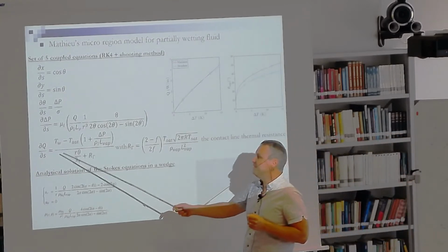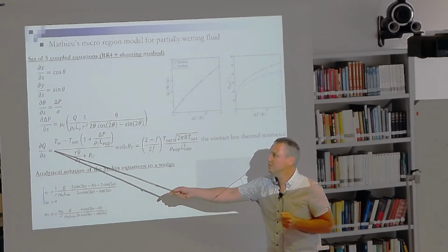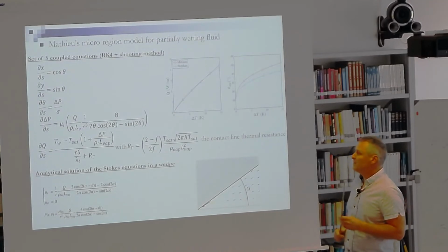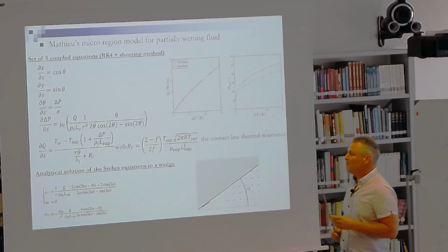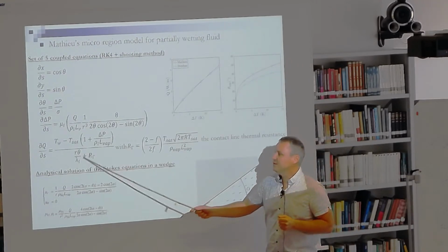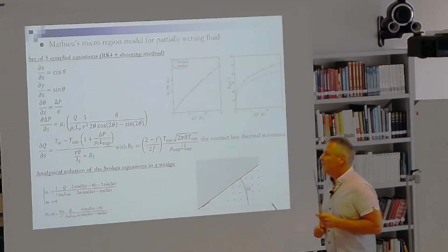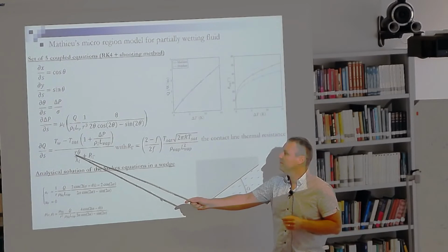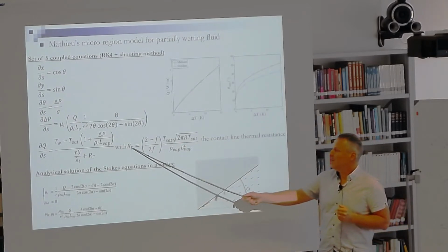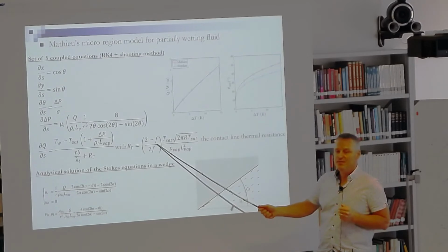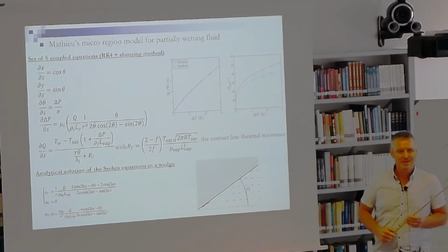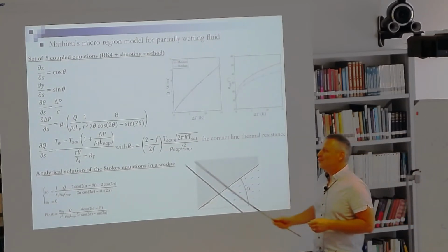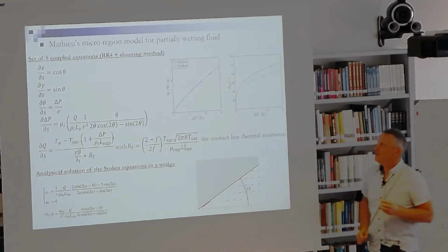Finally, we can define a heat flux distribution from this equation, which is a kind of energy equation, with some nanoscale ingredients, such as a thermal resistance at the interface, and a slip length, which also appears here. And this thermal resistance depends on an accommodation coefficient, which is not always perfectly known for every fluid. So we have to presume a value for this accommodation coefficient.